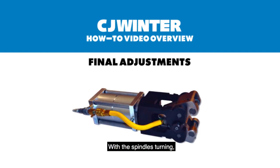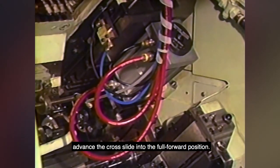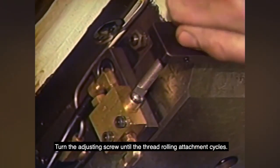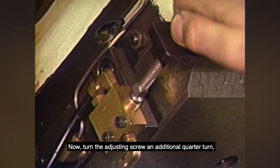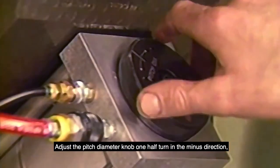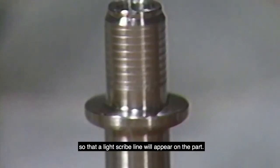With the spindles turning, advance the cross-slide into the full forward position. Turn the adjusting screw until the thread rolling attachment cycles. Now, turn the adjusting screw an additional quarter turn and tighten the jam nut against the trip bracket. Adjust the pitch diameter knob 1/2 turn in the minus direction so that a light scribe line will appear on the part.